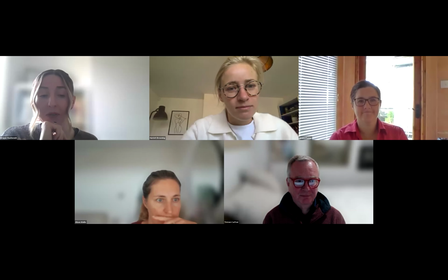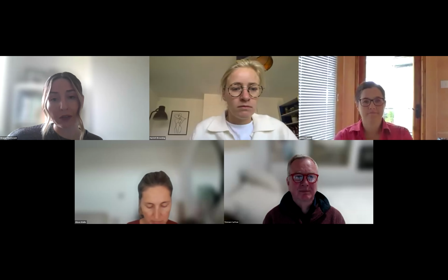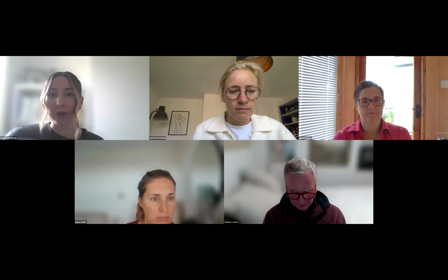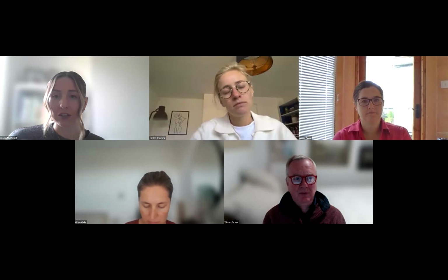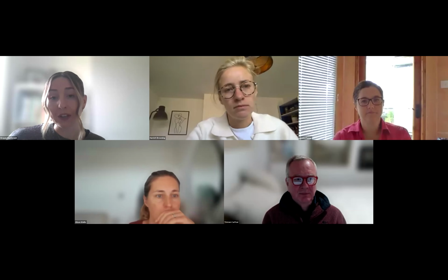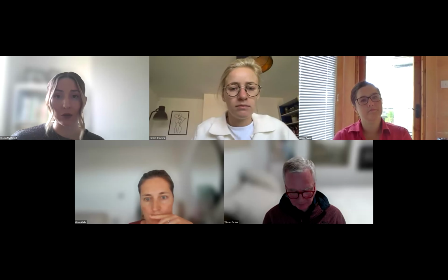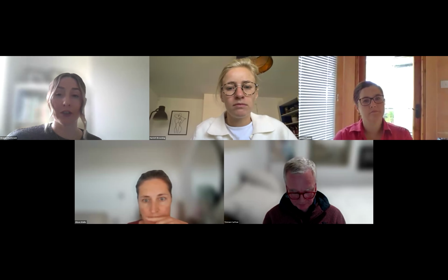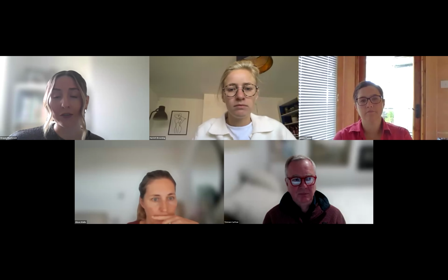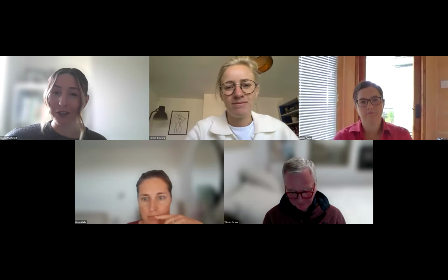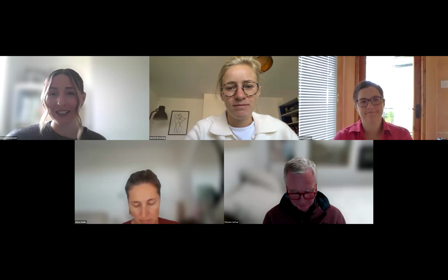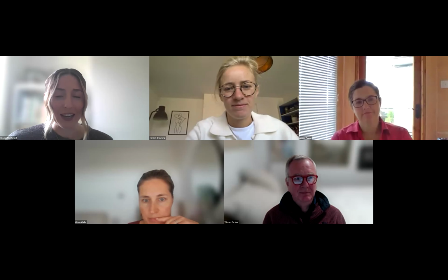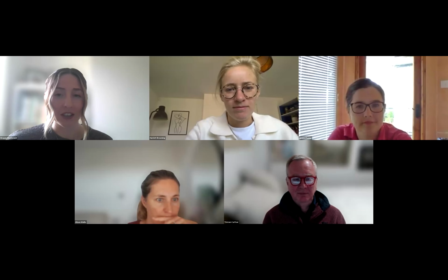Yeah, absolutely. That approach has been widely adopted by others in industry through Concrete Zero, moving towards a performance specification, which is within our control as engineers, and then the carbon limit, whether that is through a total carbon budget for the project or using the low carbon concrete group or the universal classification system for concrete. There's various ways and methodologies. So much so, the government has now put out a consultation asking for everyone's opinions on which type of methodology we should all use to look at steel and concrete. So yeah, it's still a minefield, but it's a really positive approach.